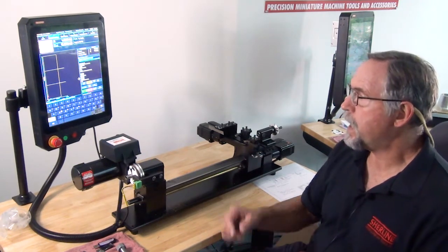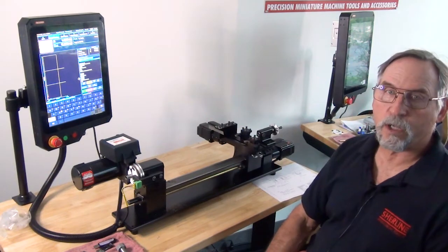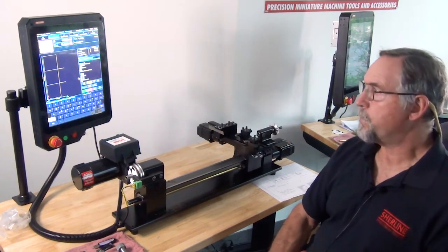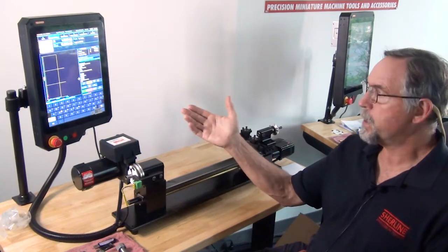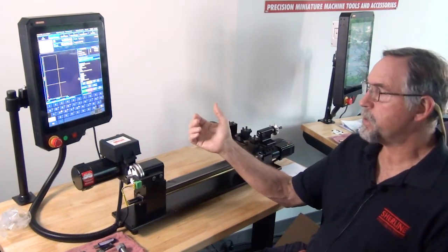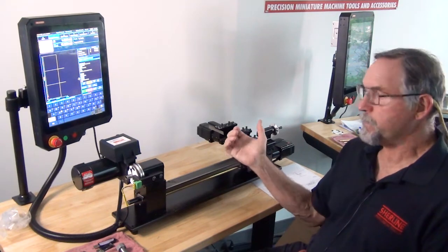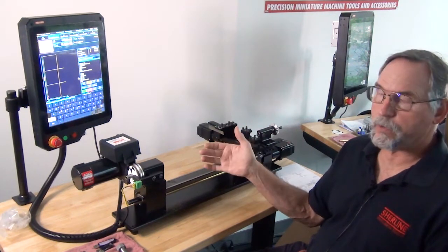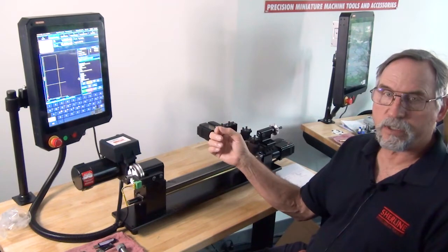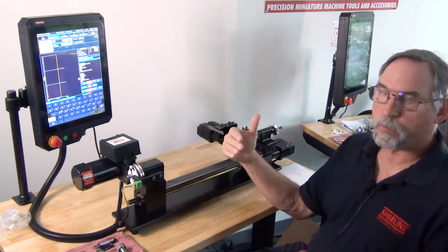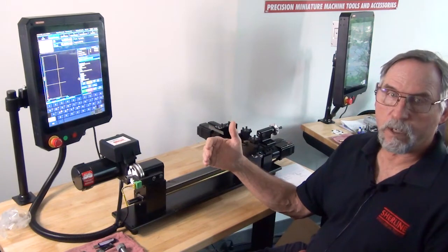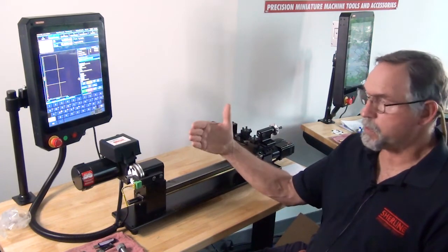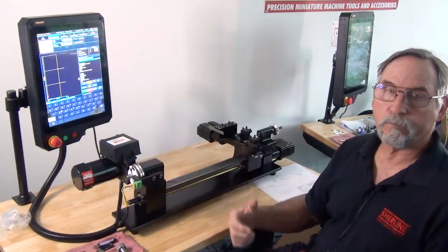To cancel the G96 at the end of the program, you just put on G97. So if I was doing a turning operation, facing operation, and I want to use G96, I would use it. If I go to drilling operation, center drill, I can just put a G97 in there, and then I can either put G94 or G95 for either feed per minute or feed per revolution for the remaining tools in the program.